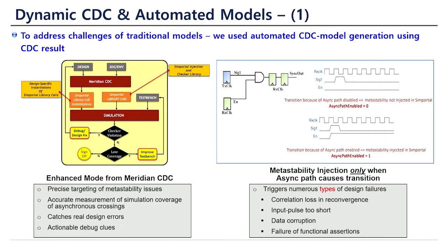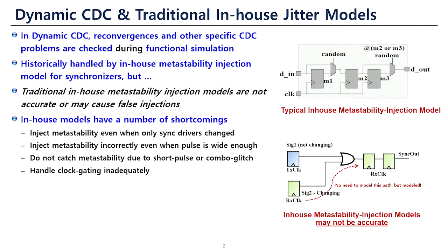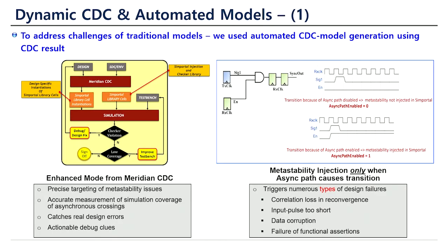So this slide shows, here, there is no problem. To refine the model, we have to monitor. In this slide, the synchronizer model shows the inside of the synchronizer. With that information, we cannot monitor what is happening outside, in the fan-in cone of the synchronizer. So to enhance the synchronizer jitter model, we have to monitor the fan-in cone logic in the figure.